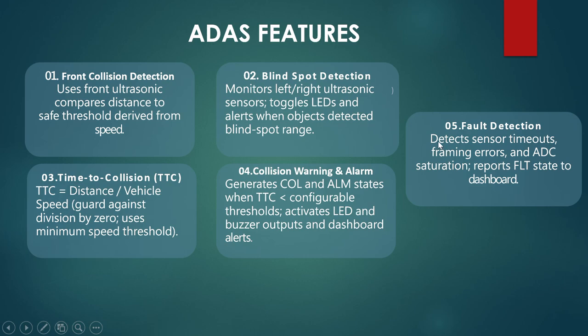The last feature is fault detection. The STM32 continuously checks sensor operation, UART communication and ADC readings. If any abnormal condition is detected, the dashboard displays a fault indication, making the system more reliable.